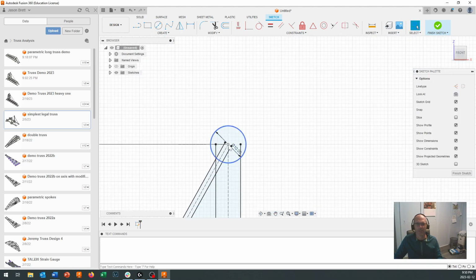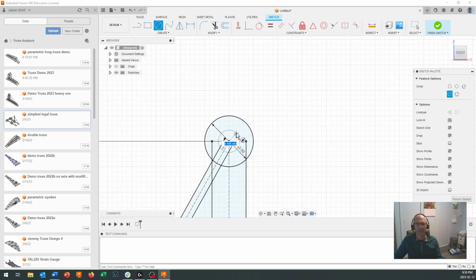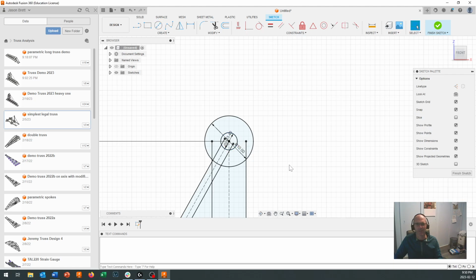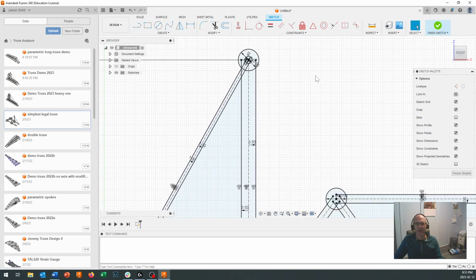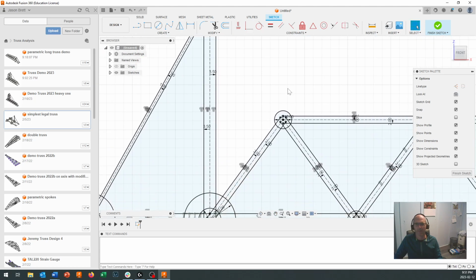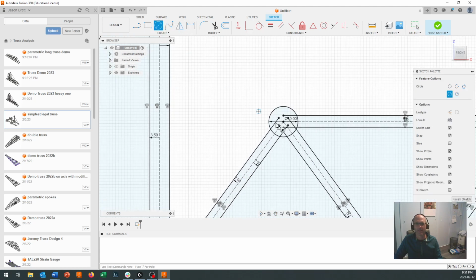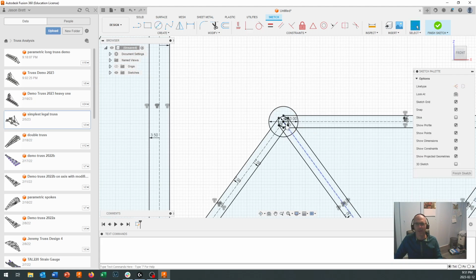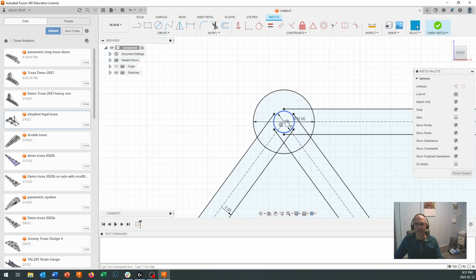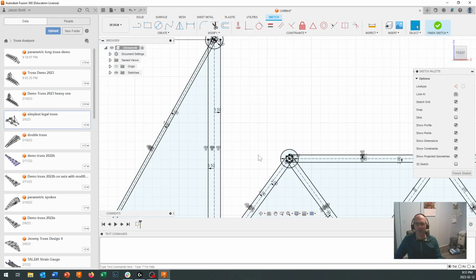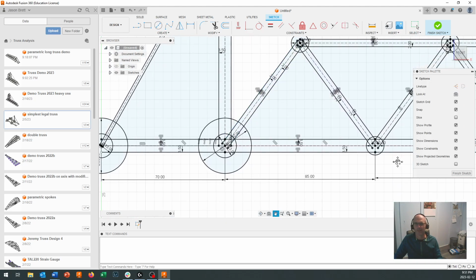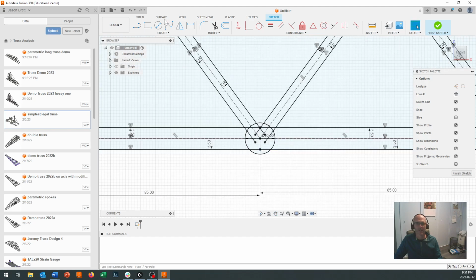And for using the small bamboo skewers, I found that 3.4 millimeters seems to be about right. But after you've done some experimenting, you may say, Jason, that's not the perfect dimension. Okay, and that one's sitting right in there. And create another circle right there, 3.4. And as we create that circle, you see you get that concentric mark showing right on there, meaning that whenever we move the outside circle, the inside circle is going to change too.